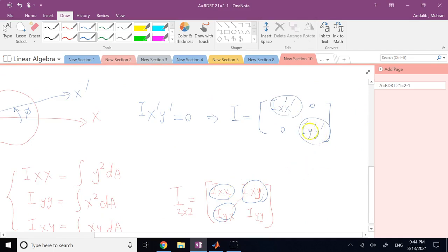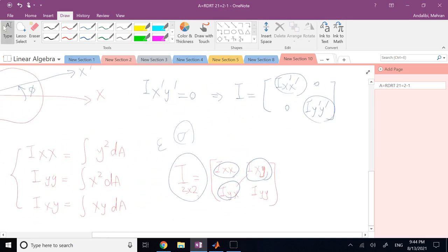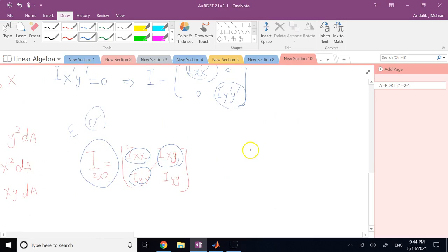If you remember, you had some formula in general, or you did the Mohr circle, or instead of the moment of inertia, this could be the stress tensor or the strain tensor. And for that matrix of stress, strain, or moment of inertia, you could calculate the principal axis, and we could calculate the angle and everything, and we had analytic formulas, and we had the Mohr's circle.